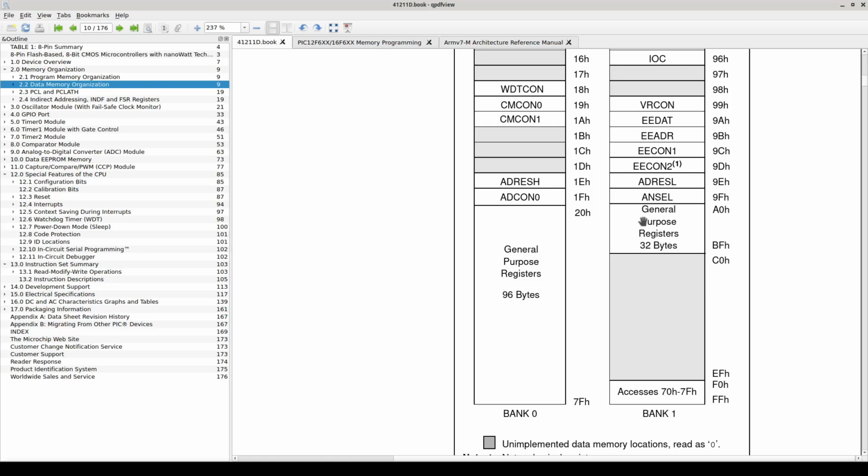I had it stuck in the back of my head that, hey, yeah, this is an 8-bit microcontroller. It's got a banked addressing scheme because we want to be able to address more than 256 bytes of memory plus control registers. But I had assumed that since there was only 128 bytes of RAM, it was going to occupy a contiguous 128-byte region of address space. And as it turns out, that is not in fact the case.